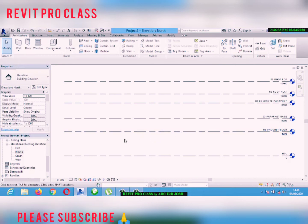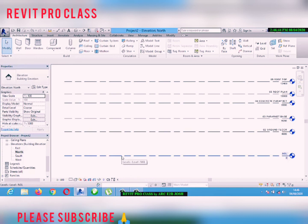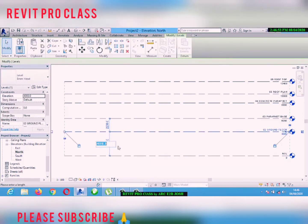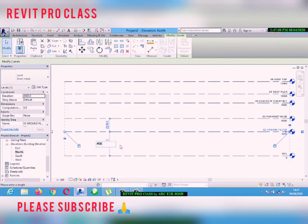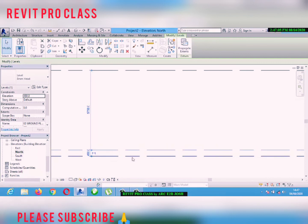You click on the second level, the ground floor, because this one is the ground, so you don't tamper with it. This is where the building is going to stand; it is the base of the building. So you go to your ground floor, click on it, then you write 450, click enter. You see this is the height at which your foundation footings is going to stop.